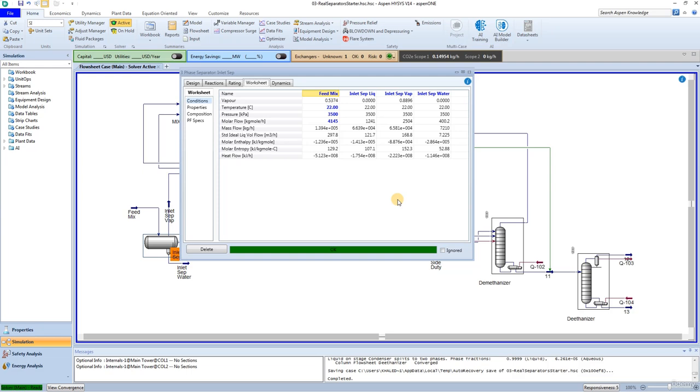Your exchanger designer is concerned about these droplets and their effect at high velocities. You need to look into using some kind of secondary separation device, such as a mesh pad or vane pad, to try and knock out these liquid droplets. Your target is to remove 99% of all liquid droplets from 50 to 55 microns in diameter.